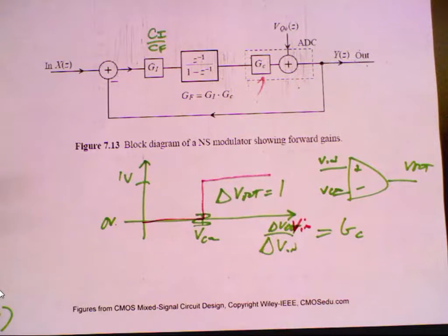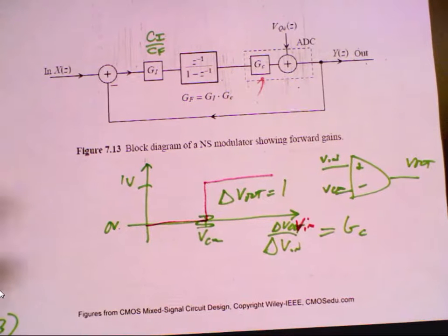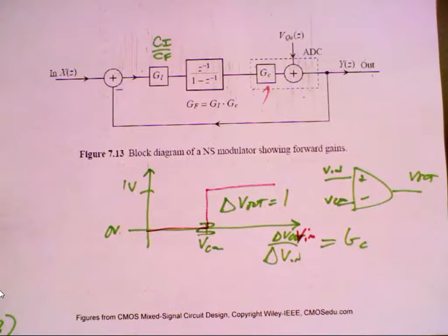I'm asking what's the benefit there? Well, it's always stable. But if the output's stuck, it's stable, but it's not worthwhile. It's not doing anything. To get quantizer gain 0, the input's above your range and the output's stuck at a level and not changing. So quantizer gain going to 0 set off a red flag in my mind, so I had to ask that question.